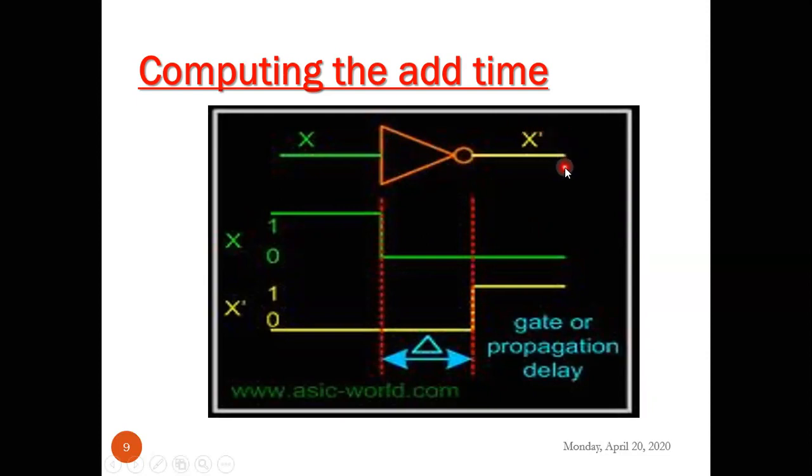Say suppose I have one more NOT gate connected here, so we call the delay at the output 2 gate delay. And one more thing you have to note, if I have one more additional gate present here, and to both the gates I apply the input simultaneously, both the gates will produce the output in the same time. So at that time, you can't say it has a 2 gate delay.